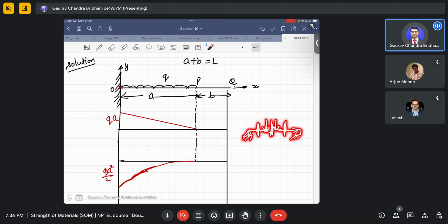Okay, it could not be that the deflection of this one and this one will be different. So you need to make sure that deflection is continuous at these points. Okay, it should not change. So that we have to take care. But as far as I know for this case, if it is an indeterminate structure, you will be given a q loading only, because otherwise you can't find the moments.